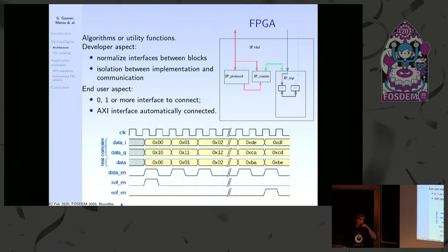But when you have a design where we want to propagate data only on an event, it's mandatory to know the start sample and the end sample of the data set. It's exactly the same for the FFT, which has a start frequency and a stop frequency. And these two signals simplify the logic per IP to handle this data set.